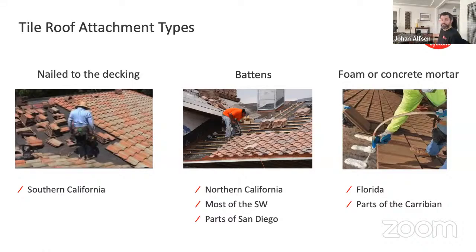So I have some tiles here behind me, and these are concrete tiles, and I wanted to show this because it does show the profile of these. You can see this is the W tile, and you can see here they have these nail holes. There's 3 of them, but typically they only use one of them. I'd be very surprised if they used all 3. Typically they use the center one. There's 3 of them because sometimes you're cutting tiles into a valley, and you have different options that you could secure them, but usually they only do 1, if any at all, depending on where they are.